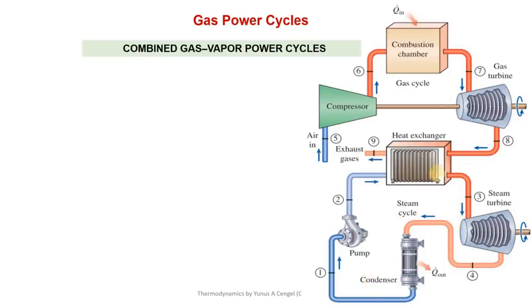So now in this way, the efficiency of this combined system may reach up to 50%, right? So for very large power plants, such systems can be used to have a huge increase in thermal efficiency. And an increase in thermal efficiency simply means a saving in the overall fuel input. So fuel is burnt only here, a part of its energy is extracted here, and the remaining energy is used here in this heat exchanger, which is acting as a boiler for this steam power plant.